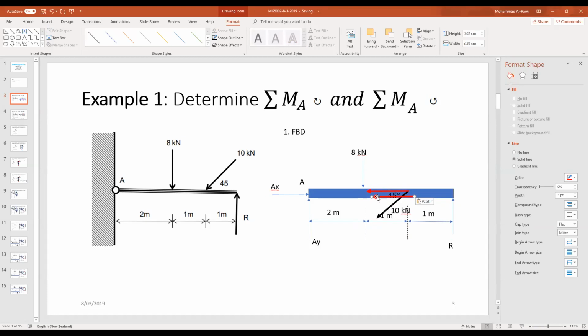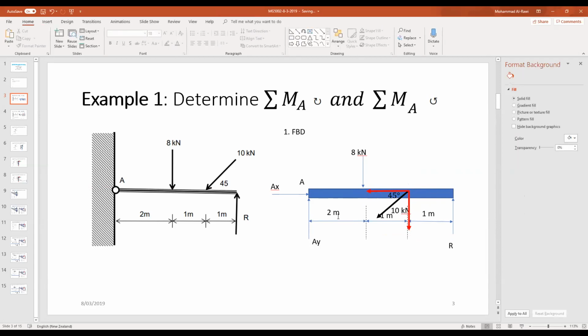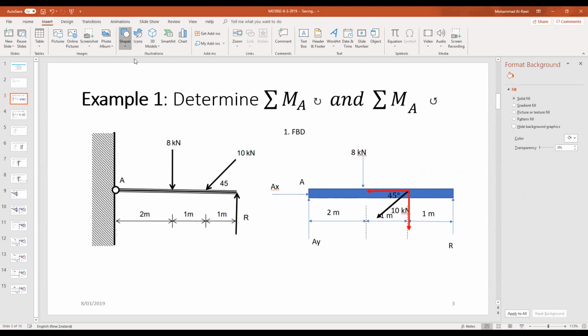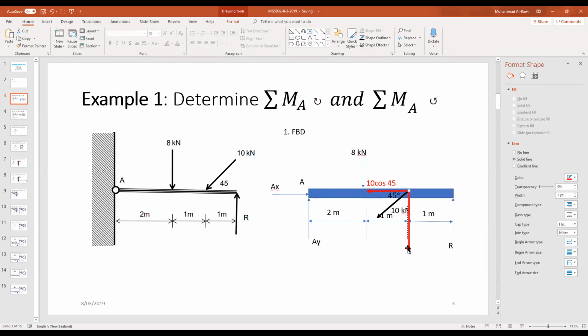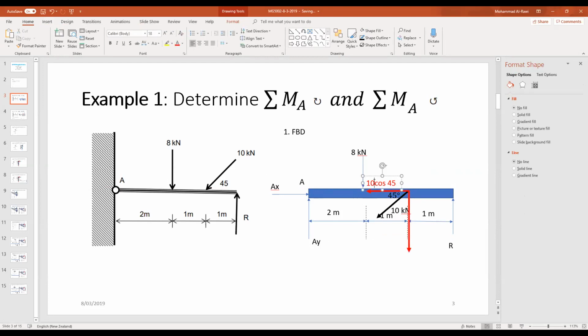And then I have another component of the force, which is going downwards. The analysis of that force should be on top of that. So if we write the first component for that one, I will just generate a new equation here. Let's say it's tan and cosine, and the angle is 45 degrees. I'll write it in red so you understand this is not part of the free body diagram. This is for that one. And the other one, I would just extend the length temporarily, just to not confuse you with other things, will definitely be tan sine 45 degrees.